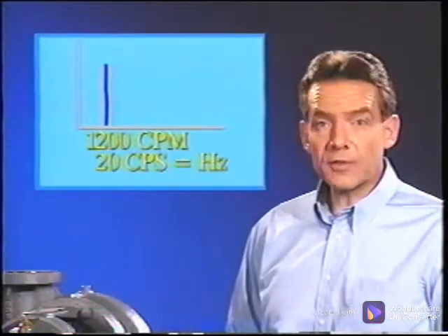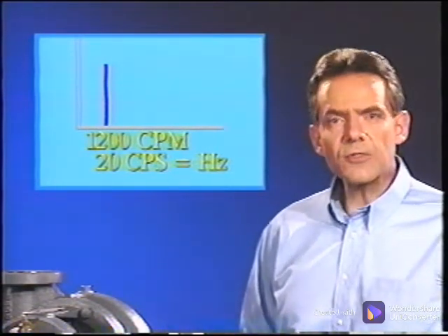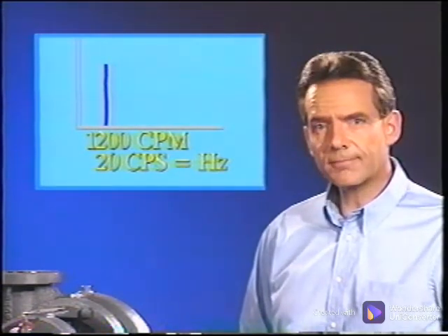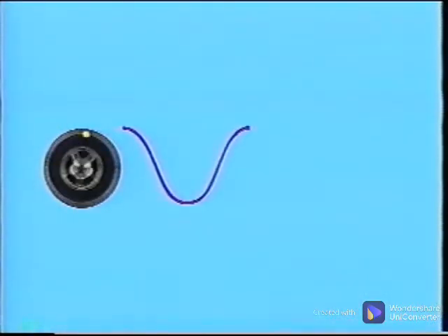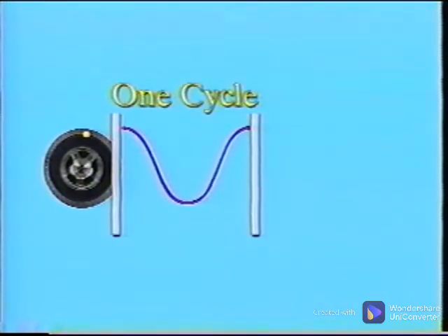These two frequency units, cycles per minute and cycles per second, indicate the precise occurrence of energy, but the analyst often compares these frequencies to the turning speed of the shaft to pinpoint the source of the energy. As we were tracing the unbalance on the tire, we noticed that the unbalance created a sine wave that started and finished at the same time the tire did. In other words, the unbalanced sine wave completed one cycle every time the tire completed one rotation.